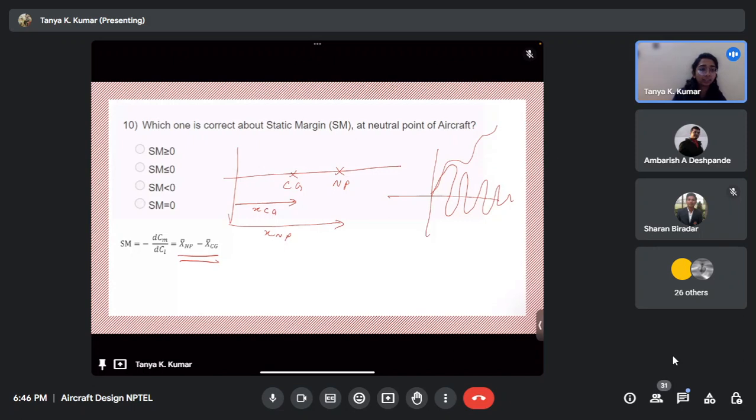Okay, so static stability is just the tendency of the aircraft to come back to equilibrium point. Equilibrium point is where the sum of forces and moments are zero. One such point is the steady level flight, or something that we refer to as trim. Trim is also equilibrium, where in the longitudinal case, your Cm versus alpha graph is something like this. Where the net moment is zero, this point is the equilibrium point. You refer to it as trim. Okay, so these are equilibrium points.